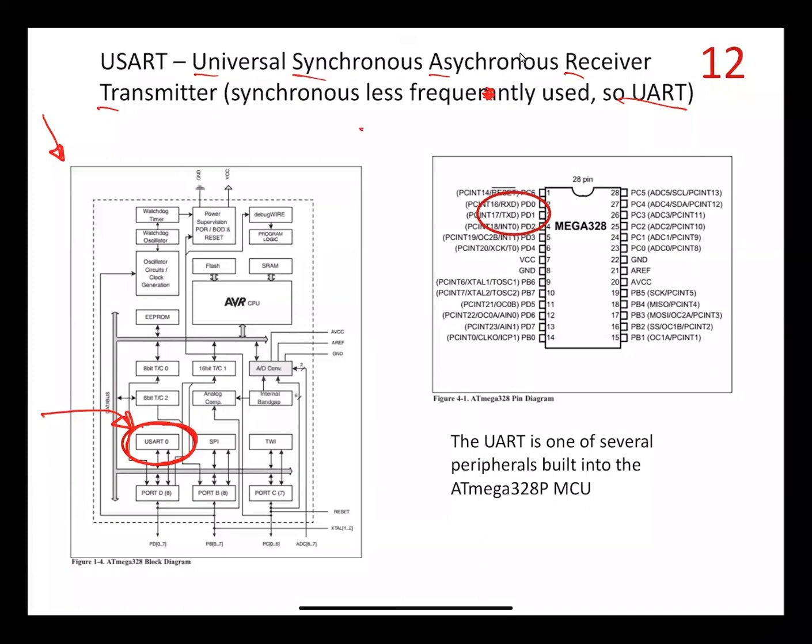And over on the right side, you can actually see the 2 physical pins that are associated with that UART. Those are just data pins, RXD for receive data and TXD for transmit data. And one thing I'll note about this is, we've previously made use of those pins as PD0 and PD1, 2 of the 8 pins associated with port D. Well, it turns out many of the pins on this chip will do double, triple, even quadruple duty. There are multiple functions associated with them.